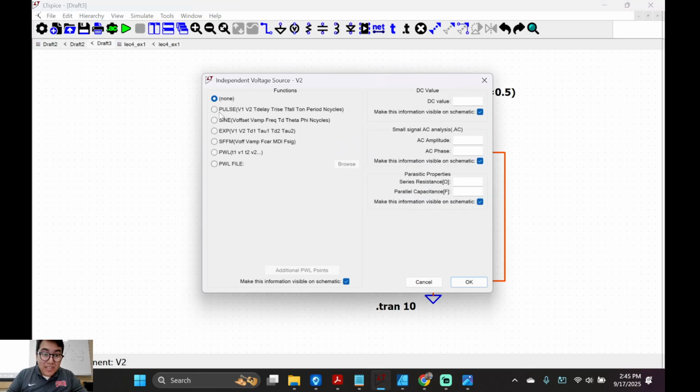Go to Advanced. It's going to be called a pulse because we're going to do a pulse. I'm going to go from 0 volts to 1 volt, because our switching voltage is half, right? Does that make sense? Does that feel confident for you? So let's wait 1 second before it does that. We're going to see it at 0 volts. My rise time, we've got to go instantaneously. We can do 1 nanosecond or 1 micro, or let's do 1 milli and see what happens. And then fall time, we're going to do 1 milli. I'm just setting how fast it goes from 0 to 1. Does that make sense? And then I'm going to have this switch on for, let's just say, 5 seconds. Is that good?